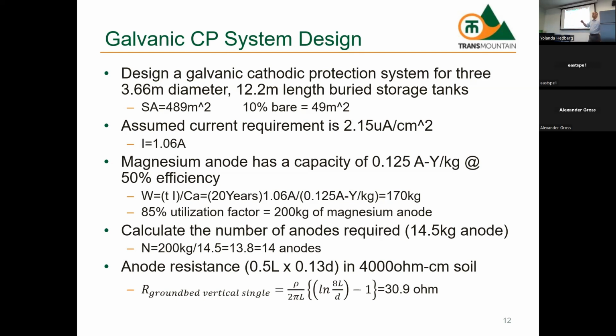The advantage to using an impressed current system is you can alter the driving voltage. I'm going to answer this just because I want to talk about it, even though it's off topic, and we'll get to impressed current systems. But the rectifier, you can adjust the voltage, right? So you can go and be like, hey, it's dry right now, we've got to crank up the voltage. You can actually get rectifiers that are constant current, so the voltage automatically adjusts for seasonal effects.